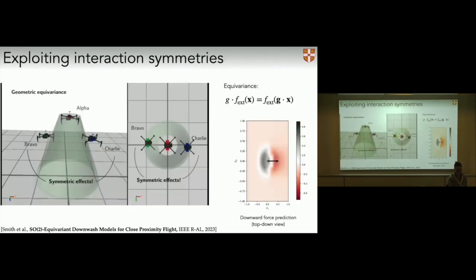Well, as you can imagine, aerodynamic patterns are complicated. And we actually used a trick in our system to try to simplify the learning process, to reduce the amount of data we needed to collect in order to get data points for all the possible aerodynamic disturbances we could have, as well as reduce the size of the model. And one really elegant way of doing this is by exploiting symmetries in the system and designing neural network architectures that implicitly represent these symmetries.